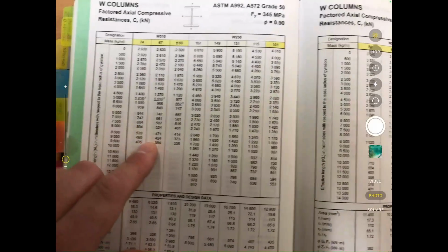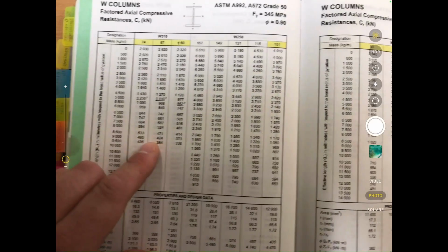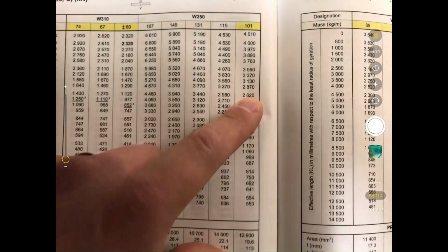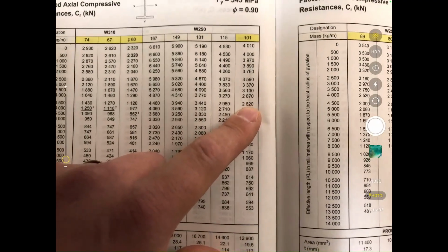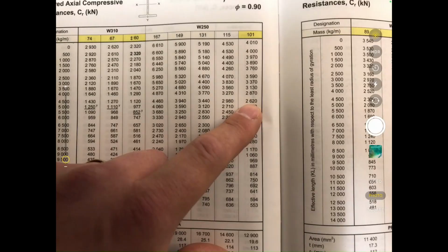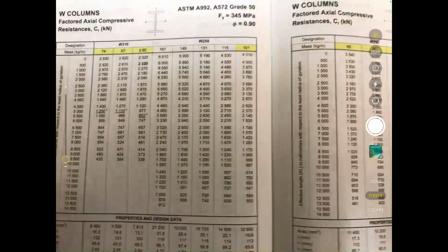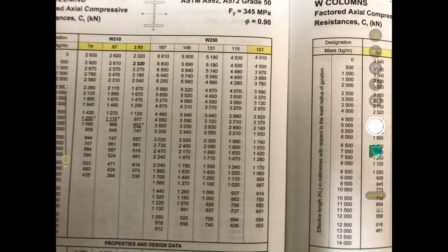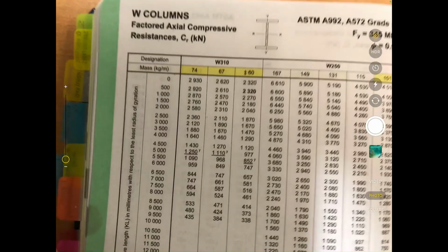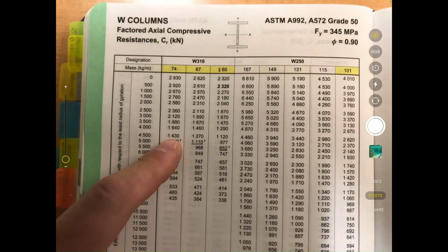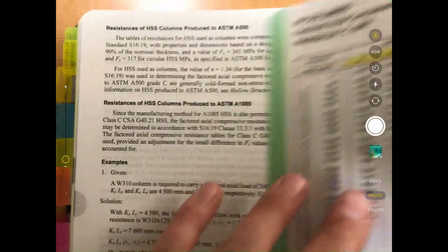Okay, so there's an available 250 by 101. It's got a compressive resistance of 2,620. It's there, so I'm satisfying slenderness. And the effective area, if I need to calculate it, is included in that as well. I'm not going to stop there, though, because maybe there's a lighter W310. So none of these W310s work. I'll turn the page,